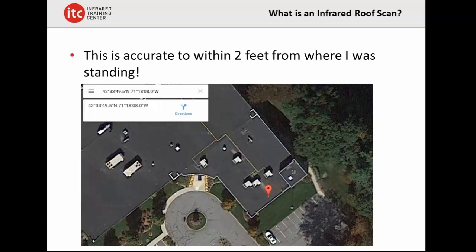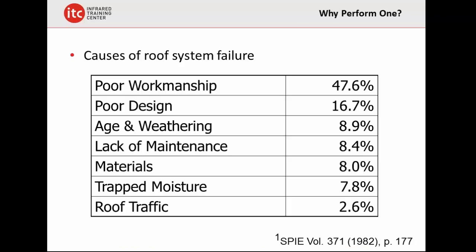So when you're dealing with camera selection, there are other options, but this is one consideration for doing roofing. Very handy, because maybe you forget exactly where you were. Maybe you just didn't mark that one particular hotspot, that one particular roof, maybe a small leak, and you want to know exactly where that roof leak was. The GPS coordinate, if it's present in your camera, will be able to give you that information.